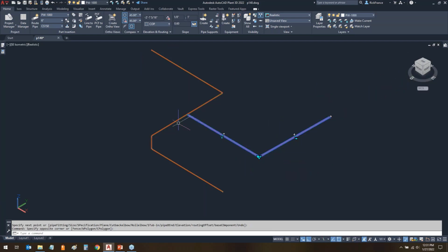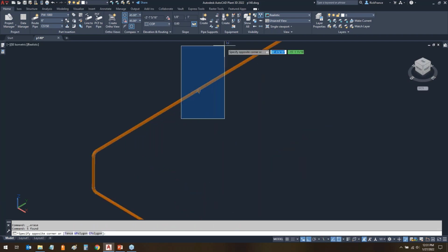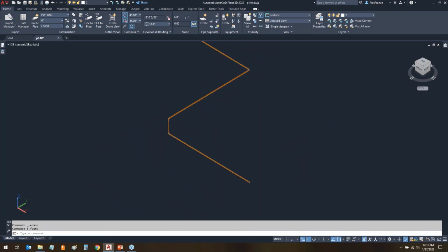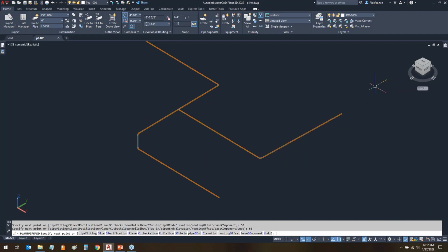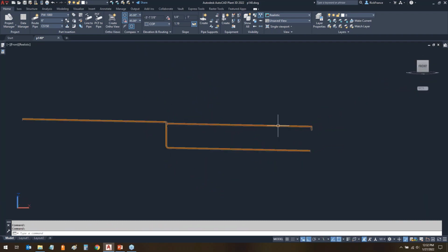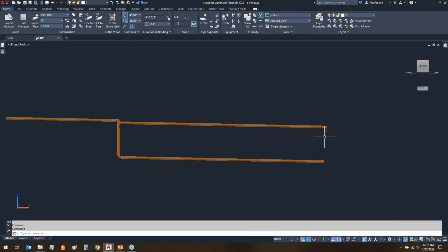Now I'm going to redo that only because I meant to change my slope to 1/4 inch per foot, and I forgot to. I've found lots of times when you change slope, it's best to click it, toggle it, to make sure the software got that change, because sometimes I've even had it happen where I've changed it, but it didn't actually take the change, and toggling it always makes it take. So we'll do that again. Midpoint, 50 feet by 50 feet. And if we look at it, you can tell it's sloped all the way.